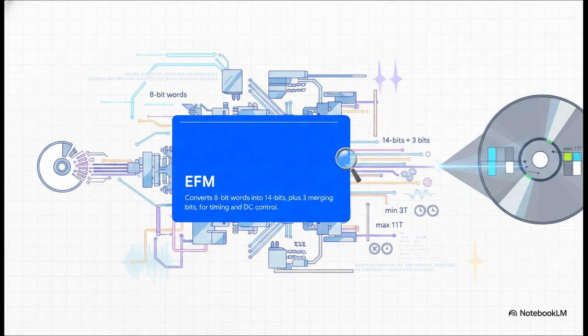To manage those millions of raw bits without physical reading errors, engineers use something called 8 to 14 modulation, or EFM. It's exactly what it sounds like, converting 8-bit words into 14-bit words and then adding 3 little merging bits between them. Why? Because the physical laser actually needs a logic state, a pit or a flat, to last for at least 3-bit times but no more than 11-bit times. Standard 8-bit data simply can't guarantee that physical spacing, so EFM completely solves that electrical issue.